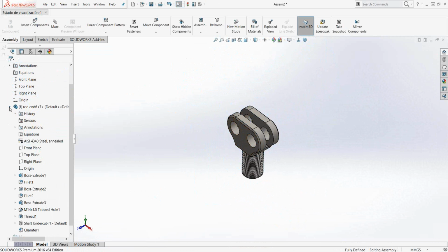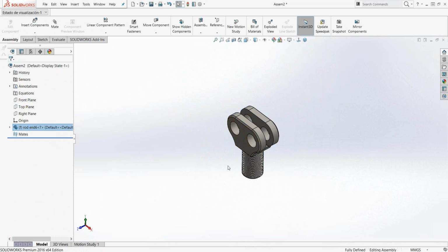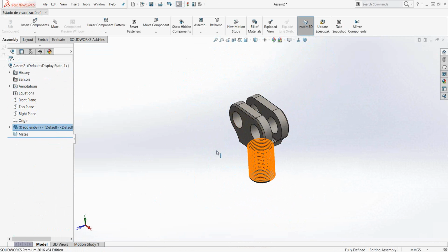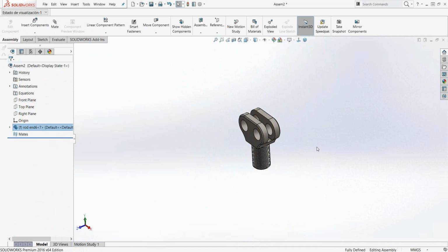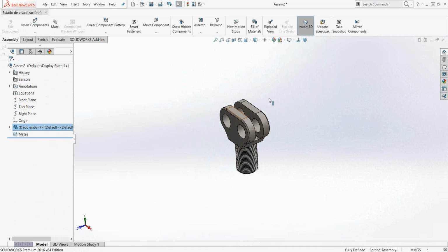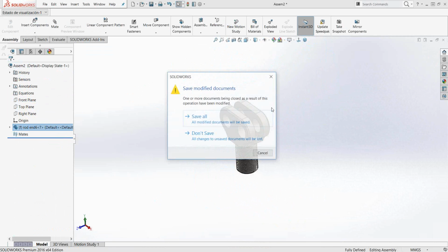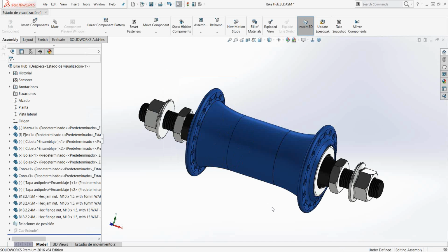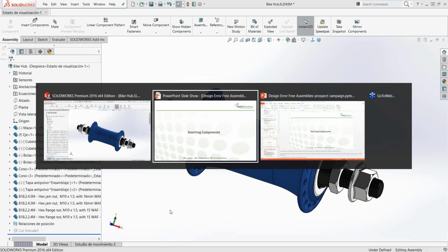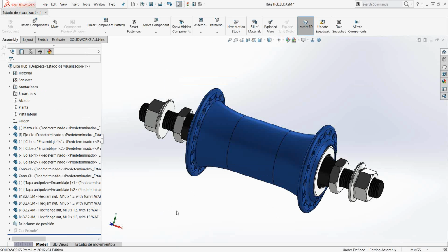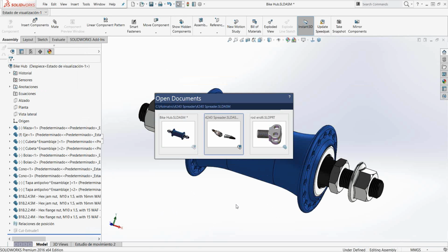You can do it either way, but if you just drag and drop and throw it in there, it's going to be somewhere off in space. If you do the check mark, then the planes will mate themselves appropriately, and that's what I prefer to do whenever I bring a part into a blank assembly and start building off of that. It's just good practice for mirroring, mating, and other things. Everything's lined up, right? So I'm going to close that out.